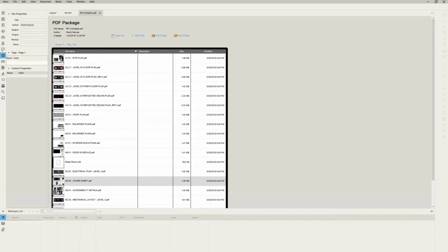And then to kind of backtrack to the comments, if you are uploading a PDF into a Bluebeam Studio session that already has markups on it with comments, those markups will transfer over to the studio session, but they become locked, and nobody can edit those comments until that PDF is essentially out of the session and downloaded locally once again. So those two kind of double up together. Thank you for adding that part about locking. That's a great add-on.